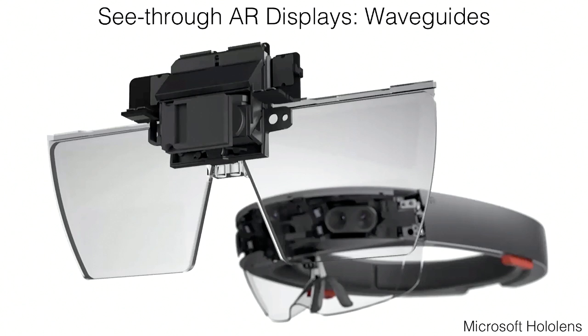I think the frontier of engineering AR displays right now is in the space of waveguides. To get to the form factor of a pair of glasses that's comfortable and small, we need to create a thin waveguide with a small projector that emits an image into the waveguide on one side, and then the eye picks it up on the other side. Ideally, we want to be able to correct the prescription of the user. We want it light, low power, and very thin. So waveguides are a great topic for research right now, a lot of interest in that space, and we're not going to talk about it more in this course.